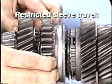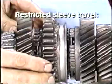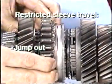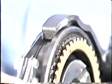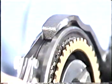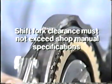The coupling sleeve must also travel far enough to fully engage the speed gears on either side. Jump-out problems can occur if anything prevents the sleeve from traveling the full distance to completely engage the gear. When inspecting a transmission, always check for excessive shift fork pad wear by measuring the clearance between the shift fork and the rim of the coupling sleeve with a feeler gauge. The clearance should not exceed the specifications in the shop manual.